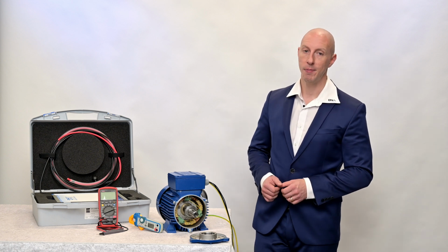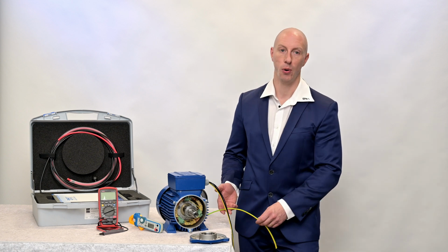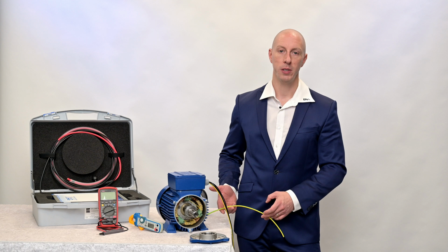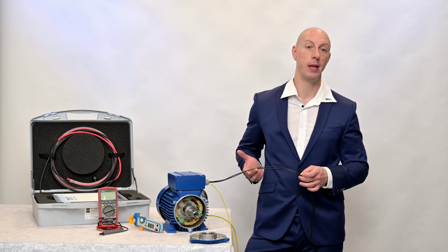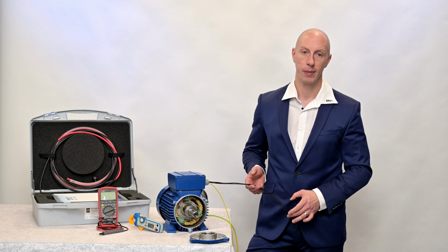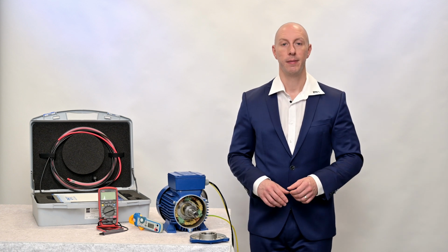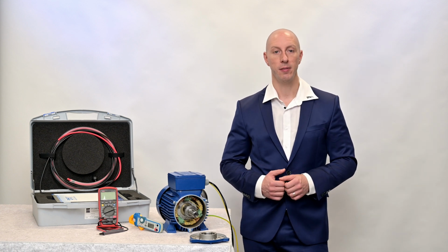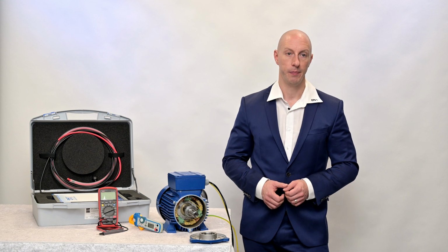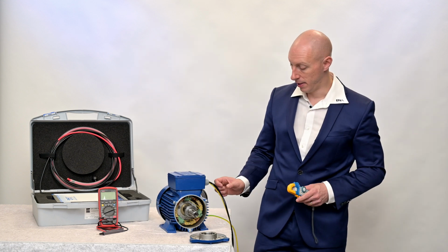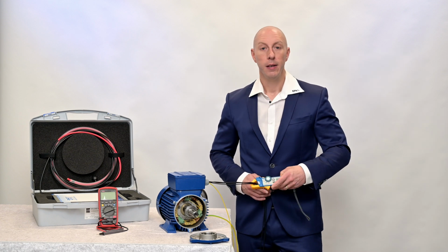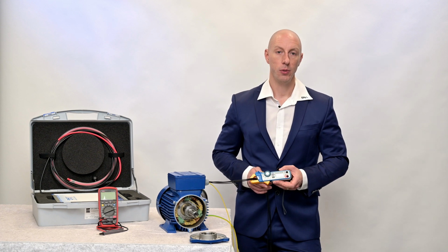This is because the current flowing through the bearing flows to earth via the earth housing and thus creates a difference in the current sum of the three phases, which should ideally always be zero. To put it simply, everything that flows via the bearing is missing in the three phases. Now it would be very simple to enclose the three phases of the motor cable within a current clamp and read off the differential current.